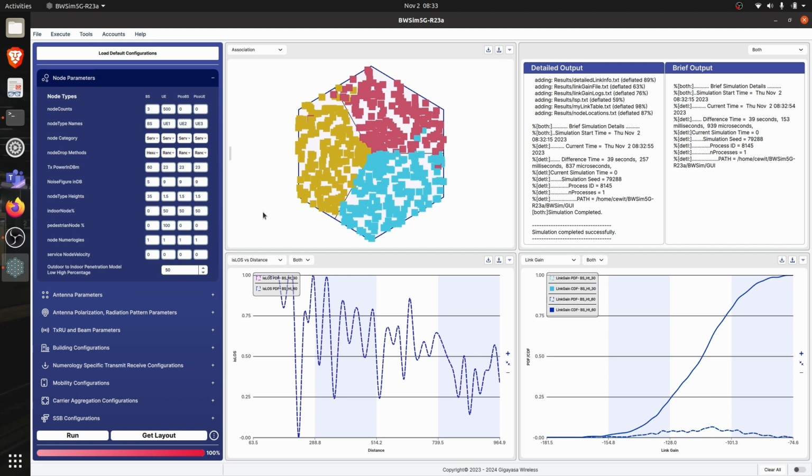To understand that, a LOS link exists when the transmitter and receiver are in the direct view of each other. However, increasing the transmitter height alone will not have an effect on the other obstructions that stand in the path between transmitter and receiver. That is the reason we are getting the same plot for different base station heights.